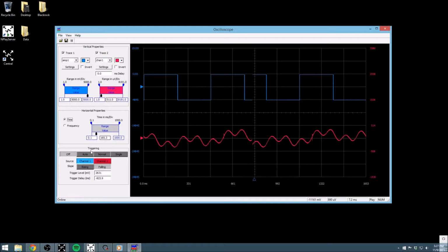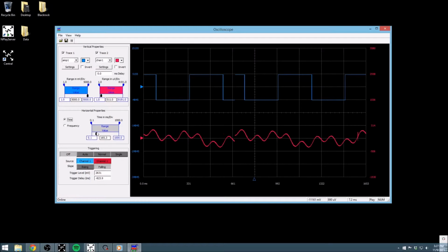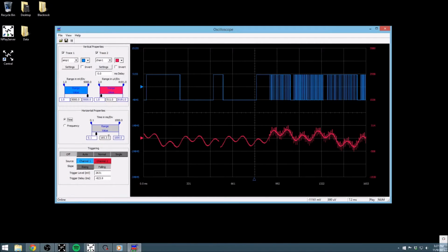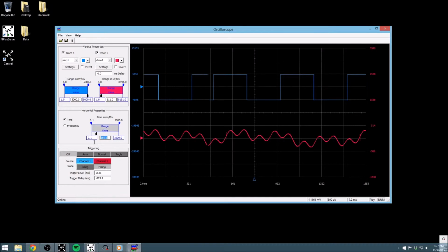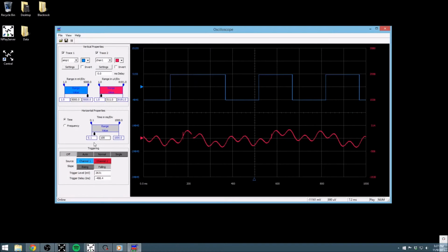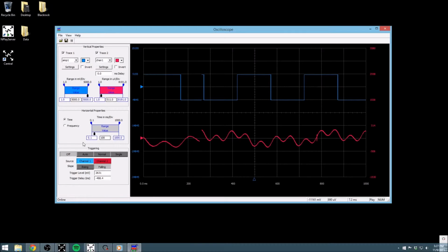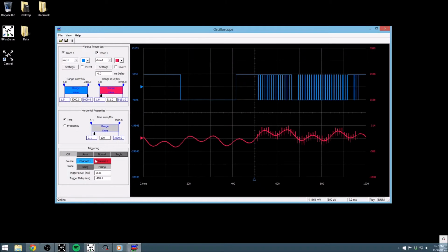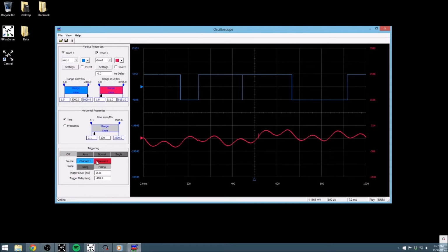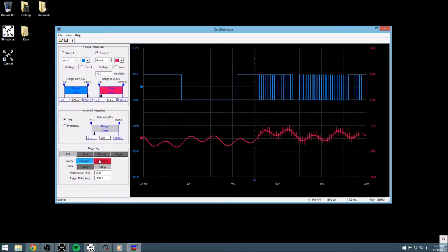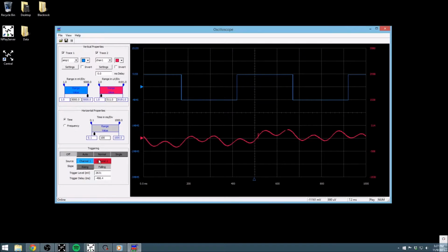I have a repeating square wave on my analog input 1 that could, for example, represent a sync pulse coming from my stimulator. I'm going to set my milliseconds per grid line to be 100, so it'll be easier to see triggering in action. Additionally, I would like to trigger off channel 2, which I have set to be my repeating analog input. I care about what happens immediately following stimulation, so I'll use only the falling edge of the signal.